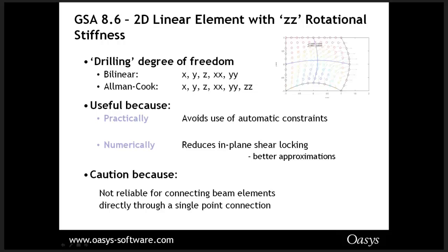So those turn out to be the exact bending strain states that are useful to alleviate problems such as shear locking that are present in the bilinear formulation. And in fact, that's the same idea with the MITC approach as well in the out-of-plane direction. So yeah, the two are quite compatible there.